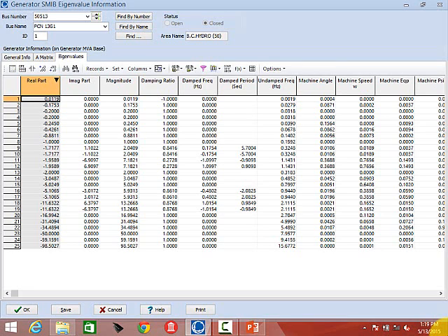Right. That's a good question. That's not on the exam, John. The answer is I'm not. And I have worked on tracking down why we have these positive eigenvalues. They're associated with stabilizer inputs when there's a bus frequency input. And this A matrix is not calculated analytically, it's calculated numerically. And I think there's some issues with that.